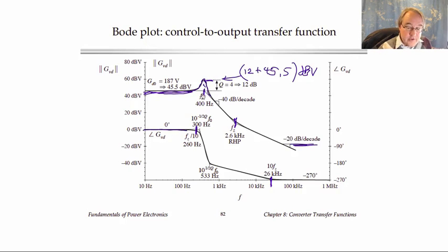And then in addition, the complex zeros contribute a slope here that's very large. The slope, recall the formula, is minus 180 Q degrees per decade, with Q is 4, so that would be 4 times 180 negative degrees per decade. So we get a very large slope over this range of frequencies extending from 10 to the minus 1 over 2Q times 400 hertz, that works out to be 300, up to 533 hertz, which is 10 to the plus 1 over 2Q times 400 hertz.